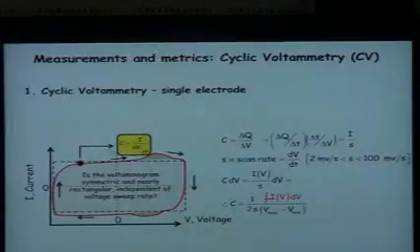supercapacitors. So the first thing that's typically done for supercapacitors, let's say an electrode, is that you take the electrode and you put it into some kind of a cell, usually a 3-electrode cell, and you sweep the voltage over the cell, okay, typically in a linear rate with respect to time. So you have some kind of a voltage increase with time that's constant, and then you sweep back at the same rate, and you're measuring the current as a function of that voltage, okay? And so you do this